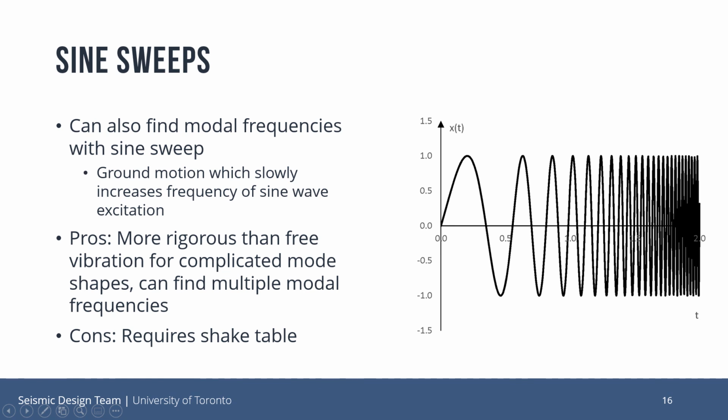And there's also issues with looking at the data and trying to interpret it. You're also going to get the frequency of the shake table shaking, and you kind of have to look at those side by side to see what's your tower and what's not your tower. But it definitely is more rigorous than the free vibration shake, especially if you have a complicated tower.